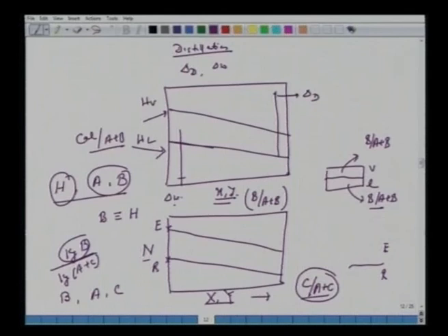So extraction with reflux is quite uncommon. It's not very popular here. It's very difficult to maintain reflux ratios, or a constant reflux ratio, in an extraction system. Mind you, every stage in extraction consists of two small units. One is a mixer and one is a settler. So to have a cascade of such units, where you have a mixer and a settler, and then you want to separate the solvent at the end and send your solvent-free solute back to this cascade of stages. Industrially, it's very difficult to do this and to maintain this purity here.